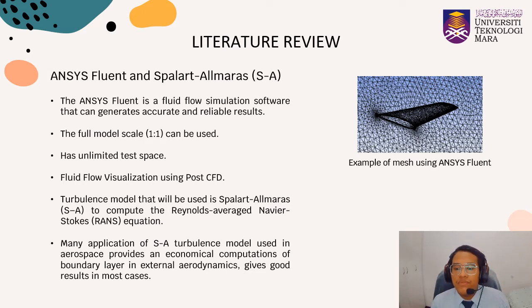The turbulence model that will be used is Spalart-Allmaras (SA) to compute the Reynolds-averaged Navier-Stokes equations. This is because in many applications in aerospace, the SA turbulence model provides economical computation of the boundary layer in external aerodynamics and gives good results in most cases.